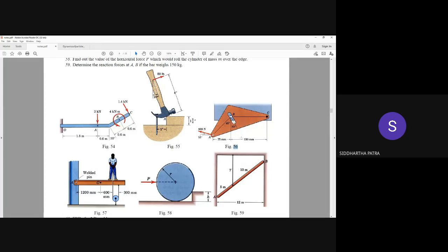Even if you are correctly drawing it very close to a normal to that line, show a perpendicular sign, the way we show one line is perpendicular to another, to clarify that it is perpendicular to that direction. What I've seen is people drawing some arbitrary direction of FB, as if FB is a pin joint. That is incorrect.